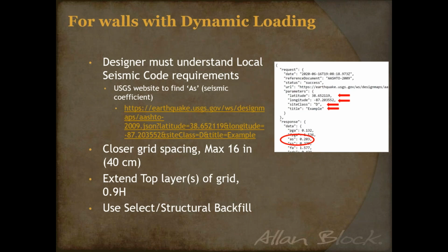Well, because retaining walls are kind of deemed a non-critical structure, where it's not a building or something like that, you can go ahead and take that value and cut it by half. That's completely up to the designing engineer and what they want to do, and if that's acceptable in the code. So just use that information as you go through this.